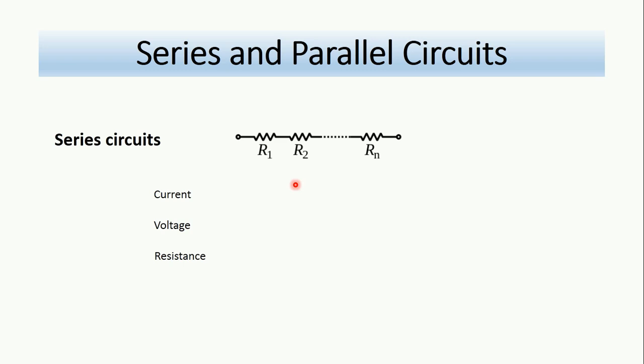Again, we have these resistors connected in series end to end as we visually see it, and we said that the necessary condition is that the current passing through all elements must be the same, and to be sufficient we need to see that the voltage drop in all elements or all resistors must be equal to the total voltage drop from end to end, and this makes it sufficient.